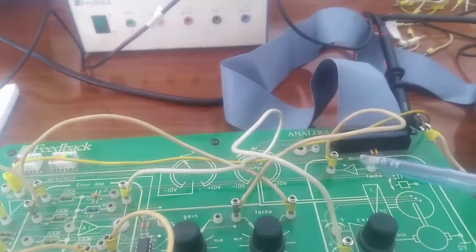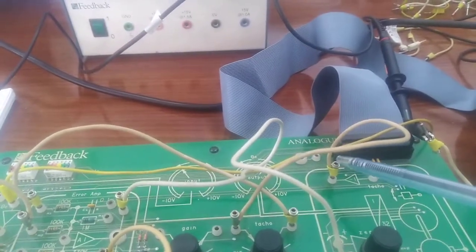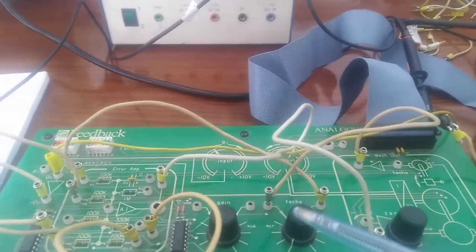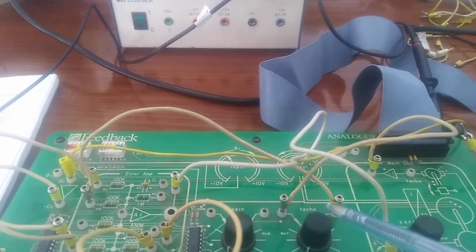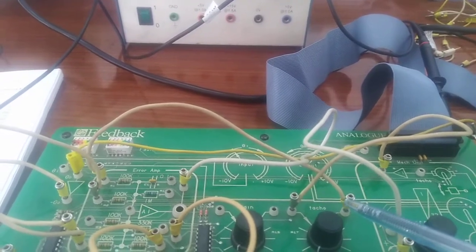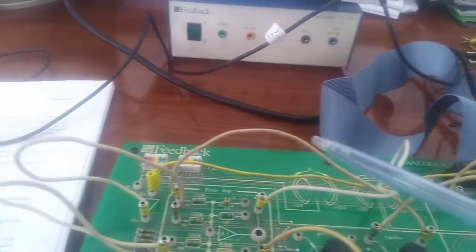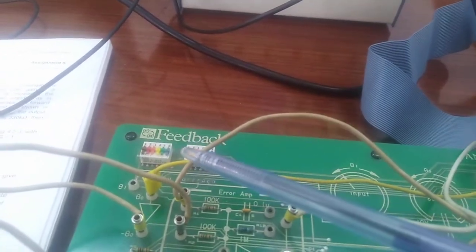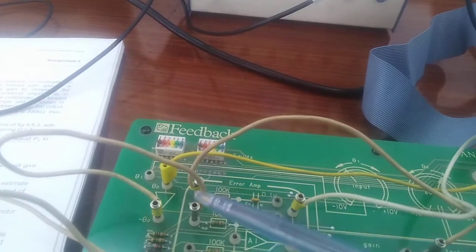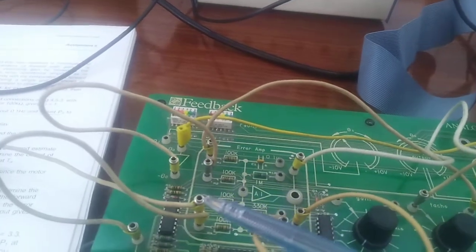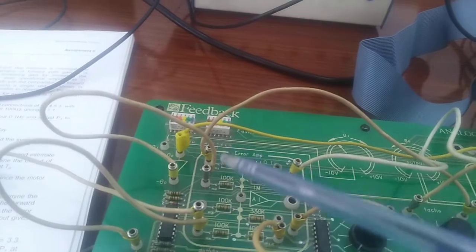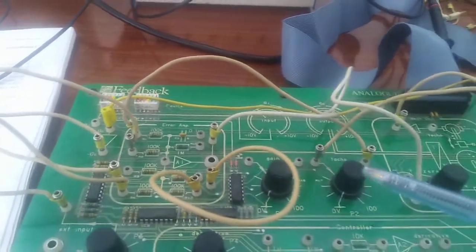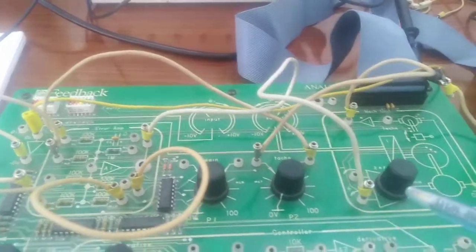Now this is the output that is coming from the tacho generator, and that is provided to this potentiometer, and through this potentiometer we can apply the velocity feedback, and that is further fed back to the input side. So this is the input side, where this is the tacho input. This is the position output rotary potentiometer, and this one is the input square wave, where all these three signals are added together and further provided to the servo amplifier and into the DC motor.